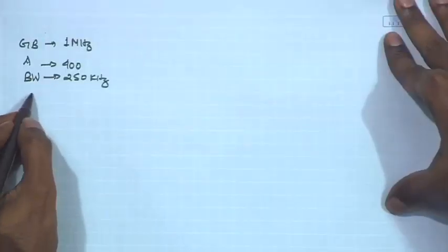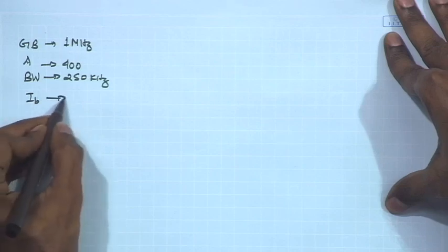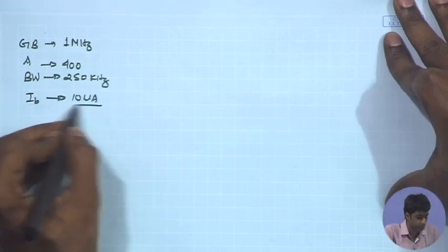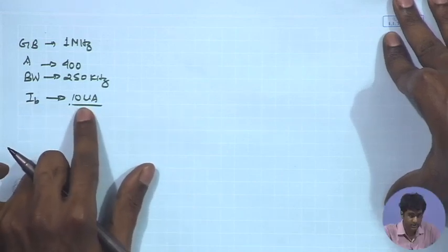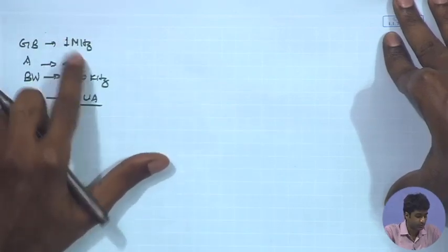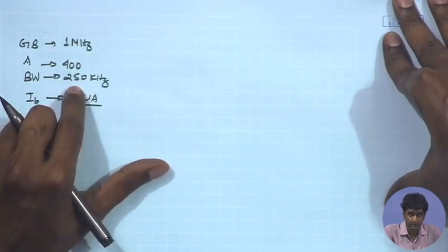If you look at the different blocks that we have discussed so far in the analog domain, the sampling switch, the ramping circuit, and the comparator, the block which is consuming static power is basically the comparator, and therefore, we expect that in the analog domain the comparator is going to be the most power hungry unit in the entire ADC, and therefore, it would be important to minimize the power dissipation in the comparator. And therefore, if I set a constraint upper limit of bias current say 10 microampere for the comparator, we can start with that constraint and see whether the most important criteria of the gain and bandwidth is being met.